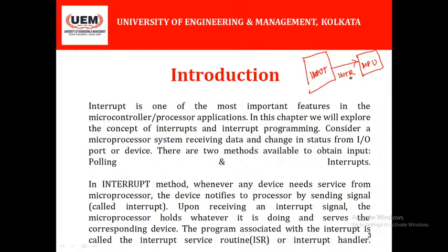Upon receiving the interrupt signal, the microprocessor holds whatever it's doing and serves the corresponding device. That means, suppose the microprocessor at that point of time is executing a program P, then it will stop that program P and will inform that input device with the help of the INTA bar that it is accepting its request.